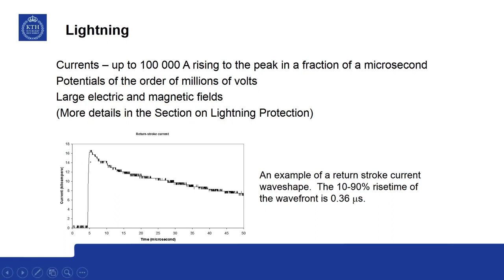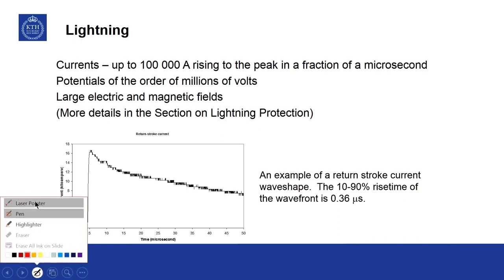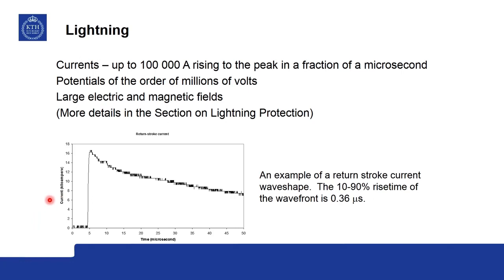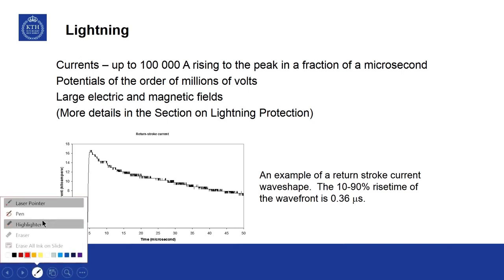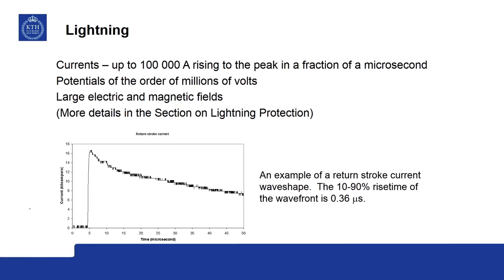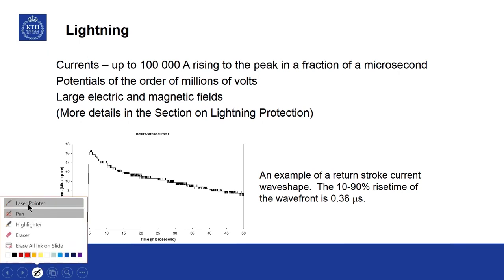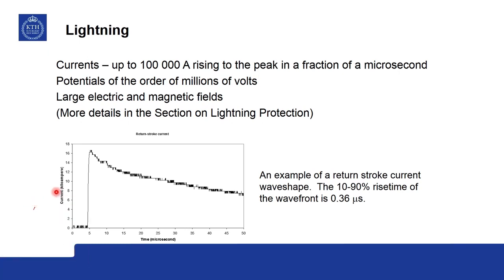This is an example of a return stroke wave shape. The 10 to 90% rise time of the wave front is 0.36 microsecond.